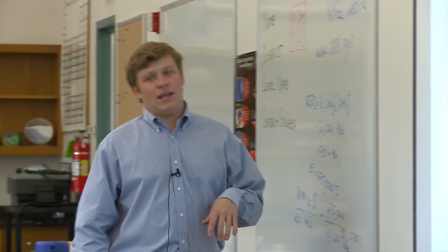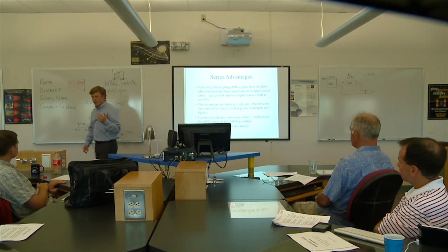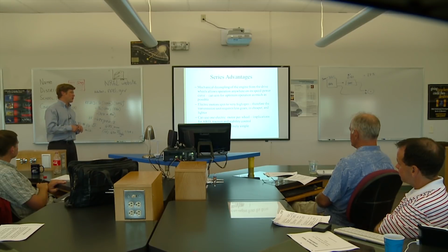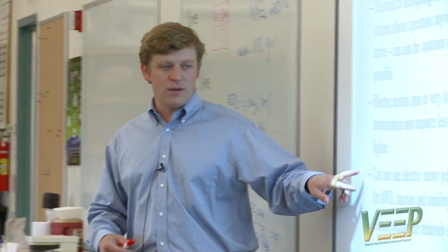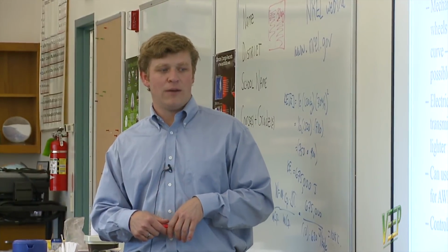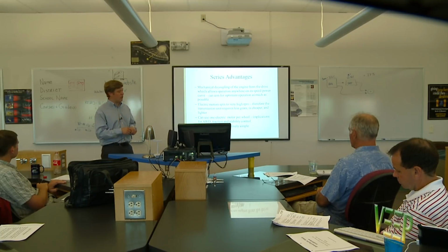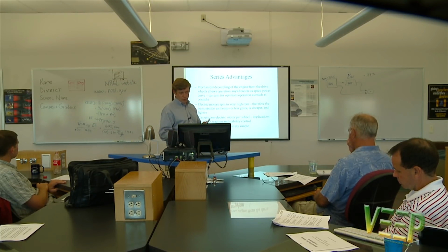The other advantage here is that it has the same advantages of an electric car. There's a wide speed range to electric motors, and a wide torque versus speed range. So you don't have to have gears, or complicated automatic transmissions and stuff like that. There's the idea of using multiple motors per wheel, or per axle, that has some benefits. And like I said, the control strategies are really simple because of the degree of decoupling between the engine and motor. Does that make sense?